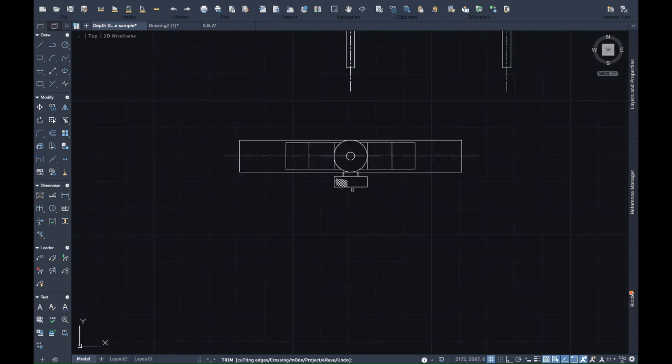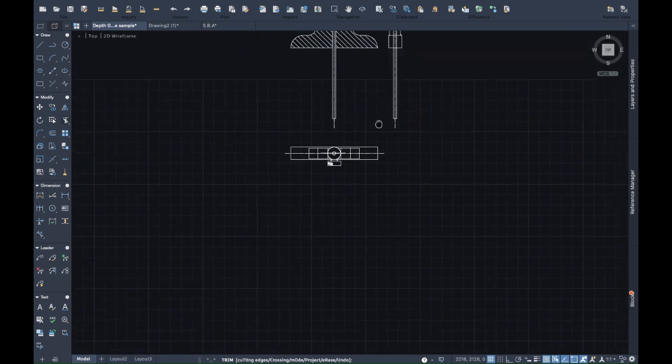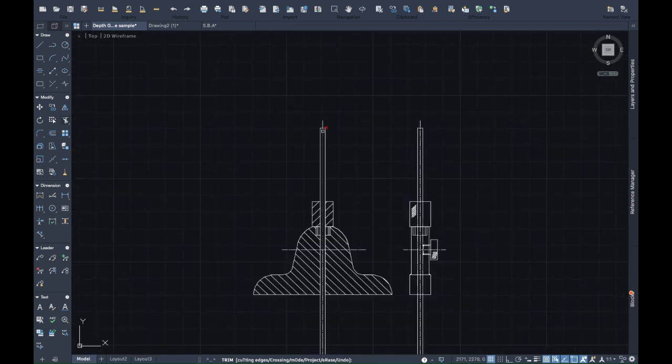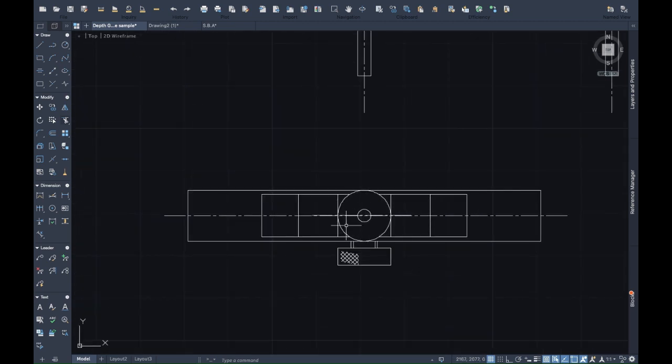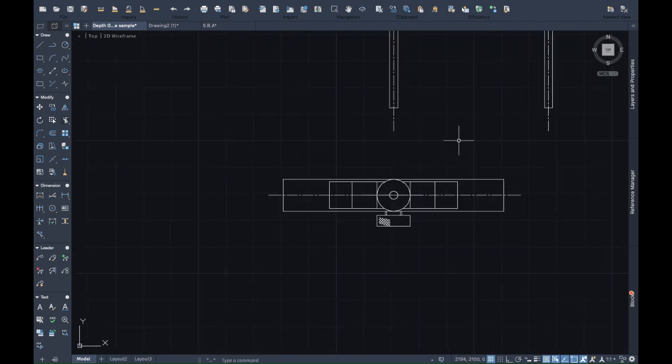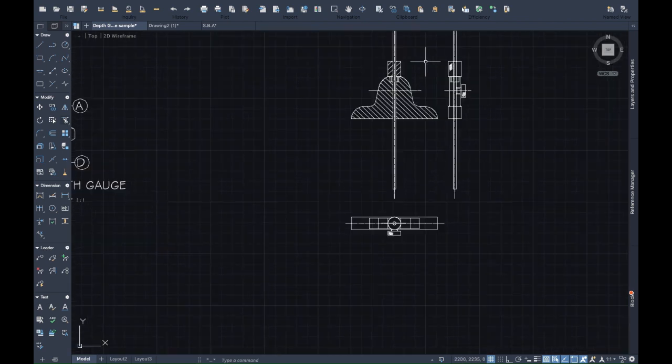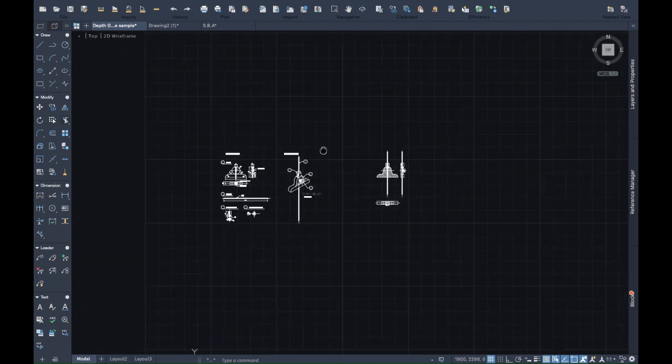Right, so here we have our screw, tightening screw, we have the spindle guide, and we have the body. Because the spindle is circular, and we're looking down on it, all we're going to see is the hole that the spindle will go in. So you will actually be seeing a solid material here. And this is our completed sectional orthographic.